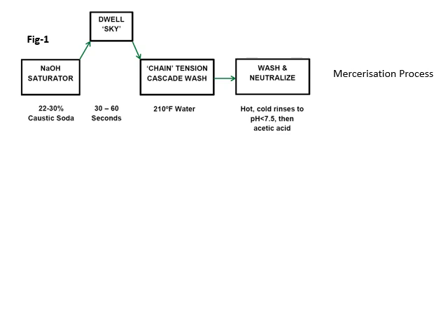This dirty water is captured after passing through the fabric. The caustic soda is thus separated from this wastewater and recycled. The mercerized fabric is thoroughly washed and any residual alkali is neutralized. The fabric may be stored wet or dry prior to dyeing and further processing.